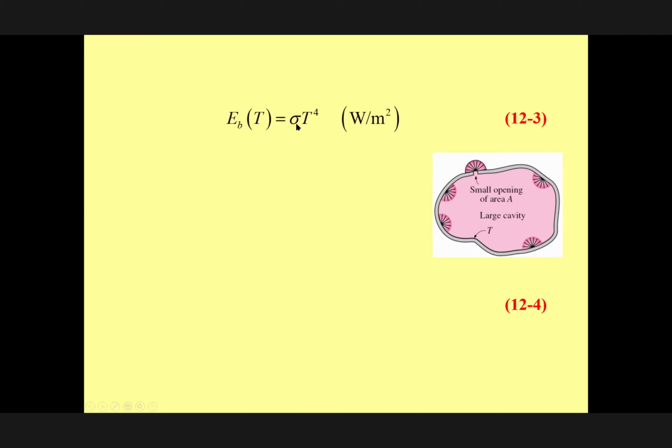Therefore, this is the maximum amount of energy, okay? Again, all of these equations, as you see, about conduction and convection, come from experiments. They realized the energy is proportional to the temperature to the power 4. Again, remember, this temperature is in Kelvin. From now on, when we use this equation, the temperature has to be in Kelvin, not in centigrade.